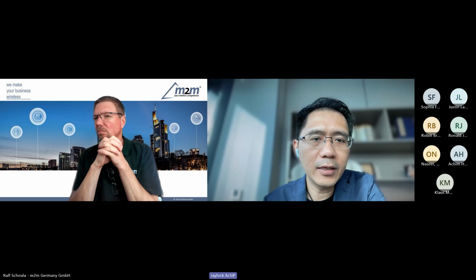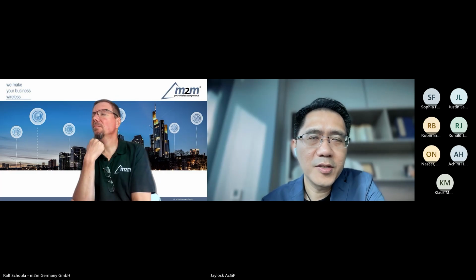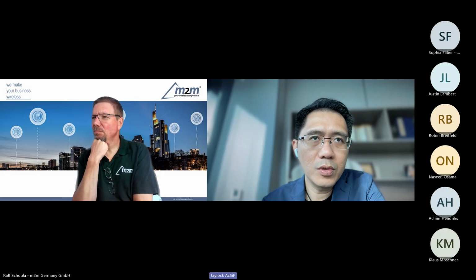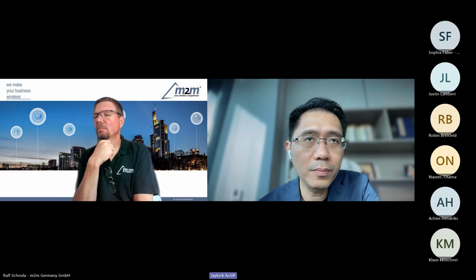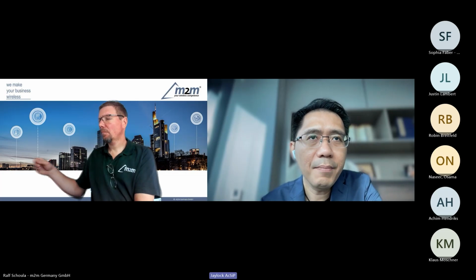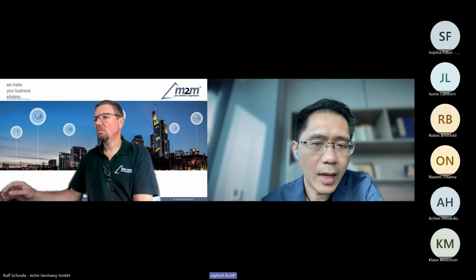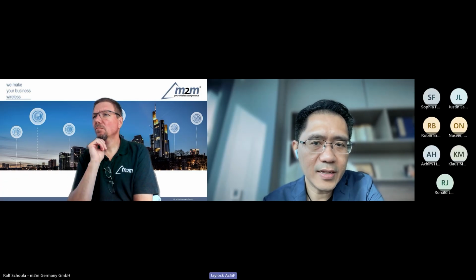I think one very successful case that we can refer to is Nordic. They had a very beautifully designed solution to resolve the Bluetooth stack certification issues. But for the hardware, you still have to go through the process if you want to go for full Bluetooth compliance. To my knowledge, for LoRa, you basically just need to go for the transmission and interference testing.